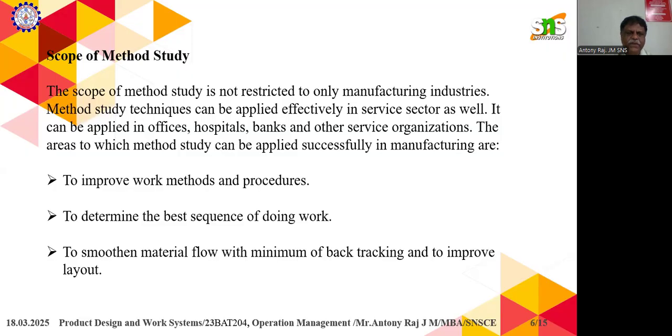The scope of method study is not only restricted to the manufacturing industry. Method study techniques can be applied equally in the service sector, such as offices, hospitals, banks, and other service organizations. The areas in manufacturing where method study can be applied successfully are to improve the work methods and procedures, to determine the best sequence of doing work, to smoothen the material flow with minimum backtracking, and to improve the layout.